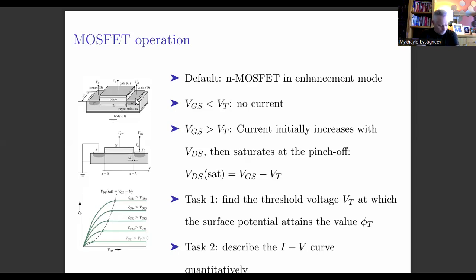All right, good. Now, if you just had the body, the source, and the drain, and they're far away from each other, then if you apply a voltage between the source and the drain, you would detect no current. But now you wish to connect the source and the drain by an inversion layer. And you do this by means of a third electrode called the gate.